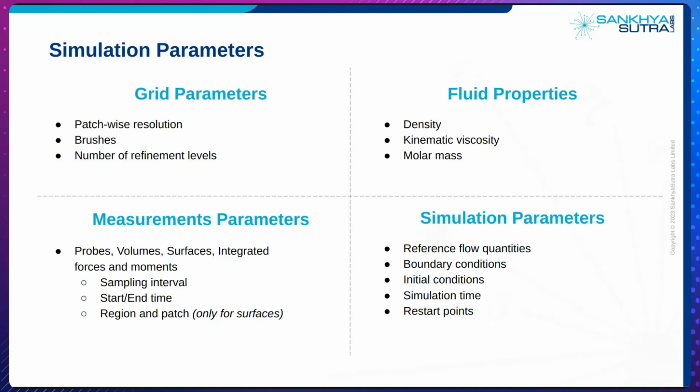For example, if you have a cuboidal domain and you want the top plane of your cuboid to have a certain resolution which is different from the rest of the domain, you are free to specify that as a user. By brushes, we give the user the facility to designate certain cuboidal regions in their domain that they want resolved with specific resolutions of interest.